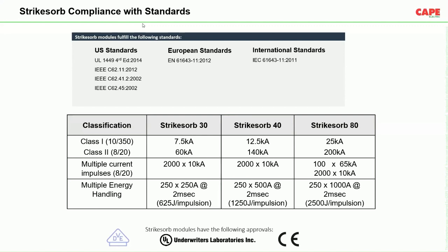So, to answer your question, the time gap between the 2000 shots is short. If you look at between each and every shot, probably 2-3 minutes at least, or even more. But continuously, it is also tested for 5 to 7 strokes without failure. The SPD didn't fail. Next question, where to put SPD in any hospital?